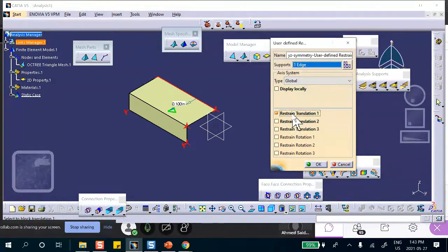Notice that 1, 2, 3 refers to XYZ in the global coordinate system. Unless you change this into user, you have to go pick it and make sure that later on you use the proper association with the user. But anyway, something else. Is this good? Does not move in X. YZ does not move in X. Should I say okay? You lose the marks for this. If this problem had 25 marks, just hypothetically, about 5 of it is going to be the symmetry constraints, and there are no part marks. So don't rush, okay?